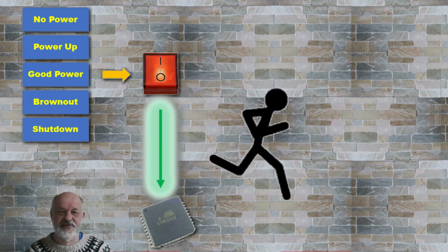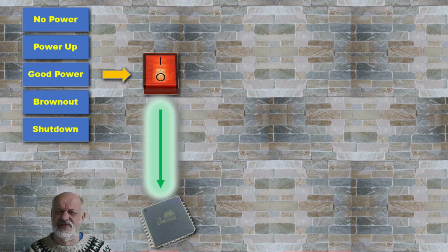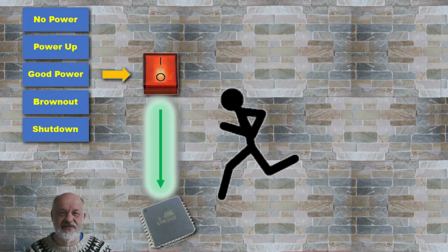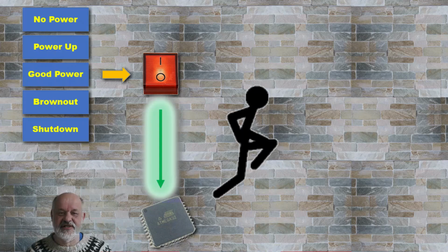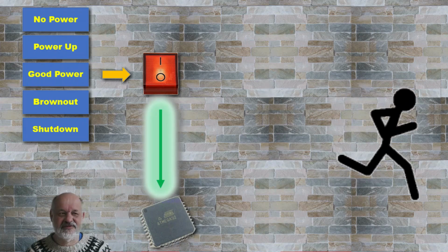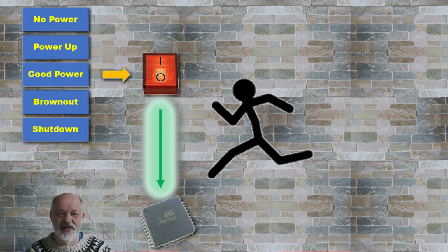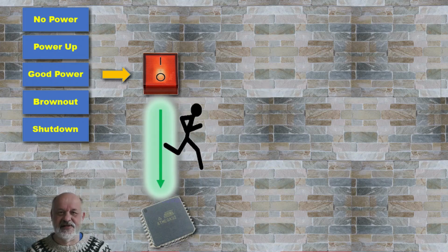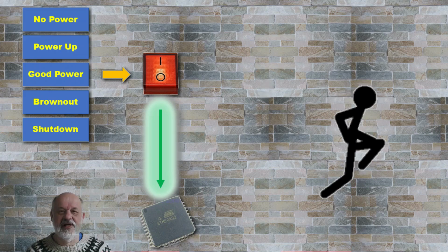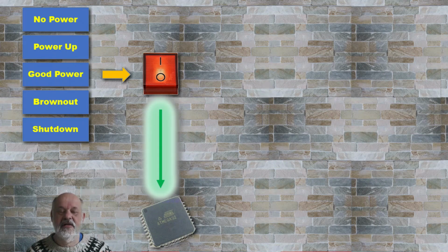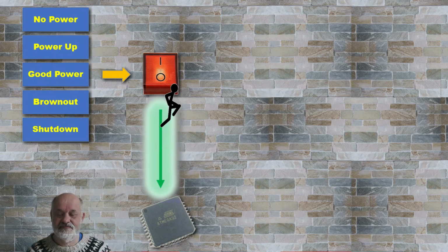Most microcontrollers today, and also the older models, contain watchdog and reset circuitry inside the microcontroller, which is adequate for most uses, but I have said this earlier, and I really don't trust that one. Therefore I use an external reset circuit, which will only release the reset pin when there is adequate power supply available.